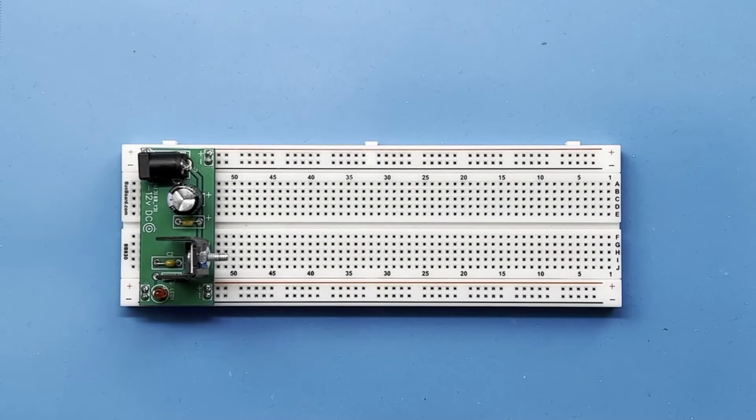So this first circuit is going to be a push button with a 555 timer set up as a monostable multivibrator to allow me to step through the clock cycles so we can follow along with the timing diagrams. A monostable multivibrator is a circuit that is stable at one output, and that output can only change by action from another component, like a push button.